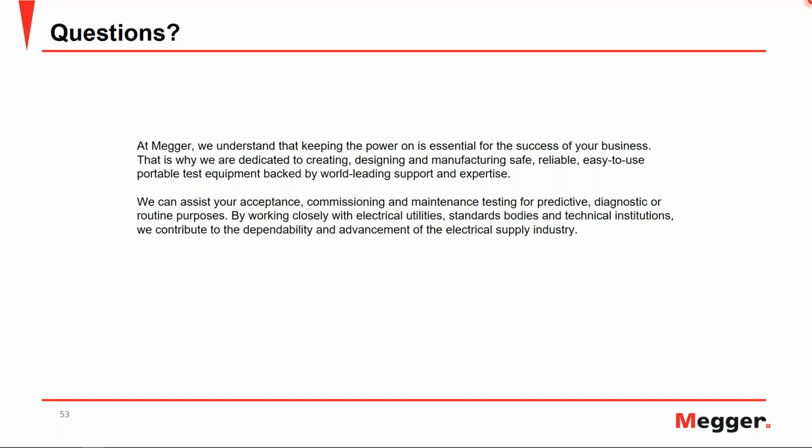There are alternate ways to perform power factor testing in the sense that you can vary the voltage and see how the insulation reacts to the change in voltage, which we typically call the tip-up test. Charles also talked about frequency-based power factor testing, where you vary the frequency and perform the power factor testing to analyze the results in a better way. Even in that, there is a narrow band dielectric frequency response, which is a limited frequency range from 1 to 500 hertz.